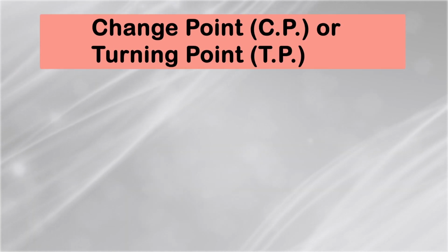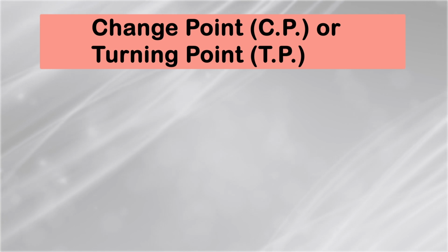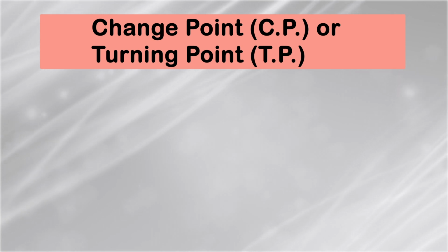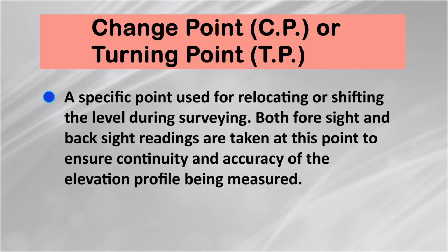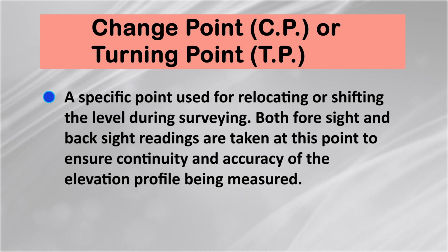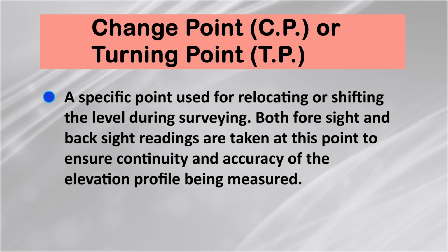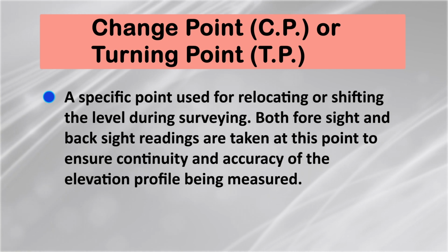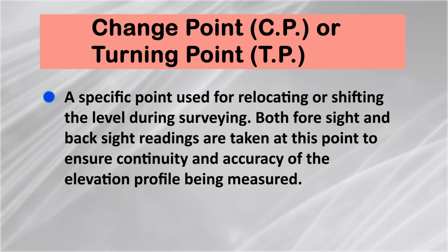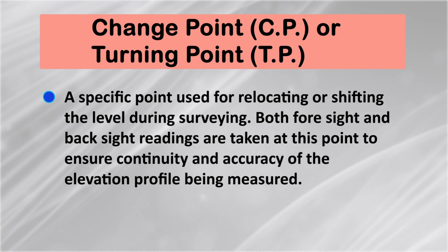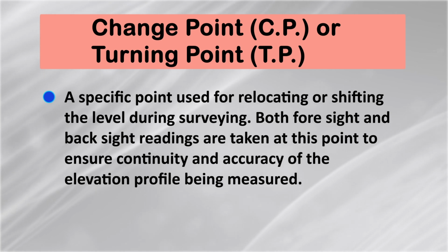Next technical terminology is change point, or we can also call it turning point. It is a specific point used for relocating or shifting the level during surveying. Both foresight and backsight readings are taken at this point to ensure continuity and accuracy of the elevation profile being measured.